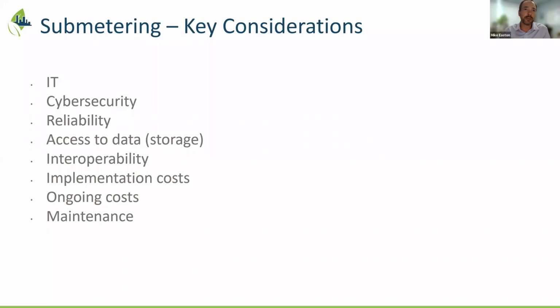But with more mechanical metering being done, there's quite a variance in the amount of re-verification and recalibration periods necessary. If we mentioned Measurement Canada earlier, if you've got a Measurement Canada approved meter in, say, for gas, or a utility grade meter in for water, you're probably good leaving that meter in the field for 8 to 10 years before even needing to check its accuracy, because there's so many of those deployed at a utility scale. The accuracy of those meters is very good for the long term.